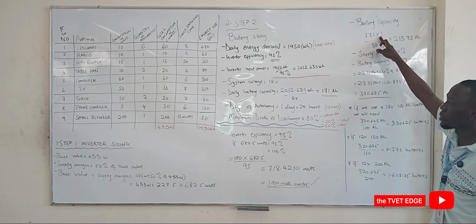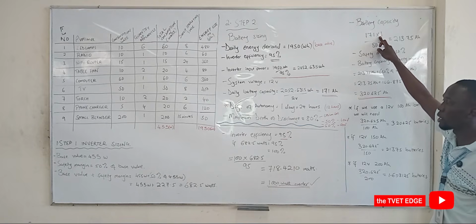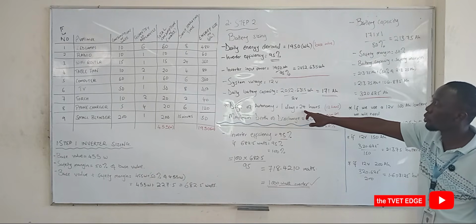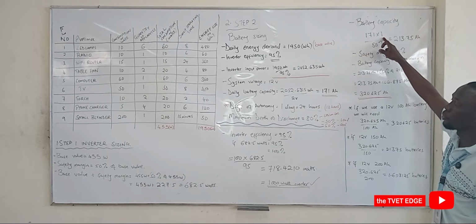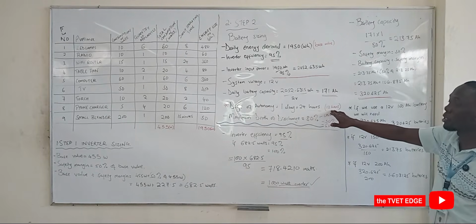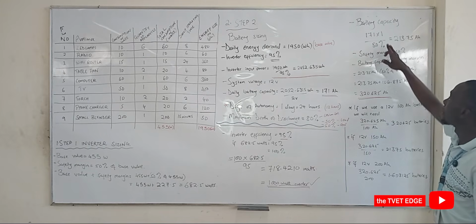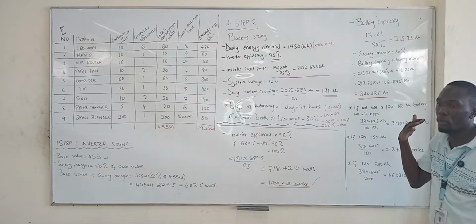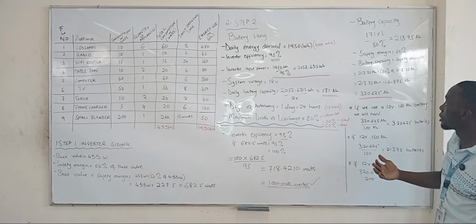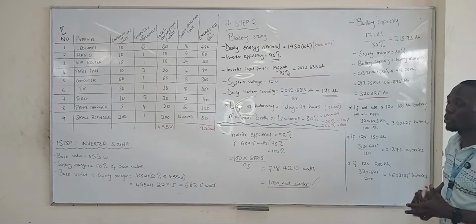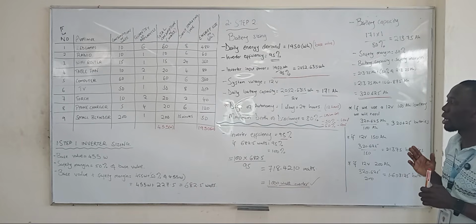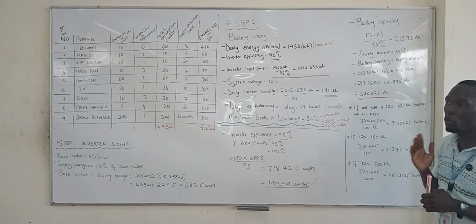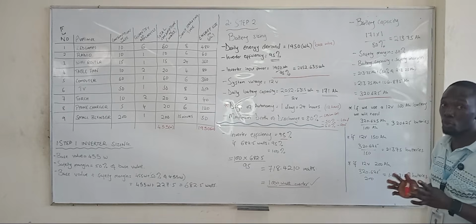If you want to size your system to just run probably overnight, I'd still encourage you to use 1, but you can use 0.5, meaning to assume that this system will only be working for 12 hours overnight. But for the right practice as a technician, for the very minimum days of autonomy, I'll encourage you to use 1, never go below 1. As good practice.